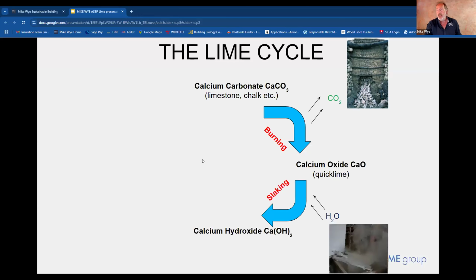So we have quicklime. Our processes here at Mike Y, as I'm sure many of you else in the industry would also be familiar, we're taking quicklime and in our operations here, we're slaking it, which means putting it with an excess amount of water. You get a very, very vigorous exothermic reaction, lots of gas, it boils in its own reaction effectively, lots of heat, and this results in a milky, creamy fluid, which is then left to settle in tanks for a number